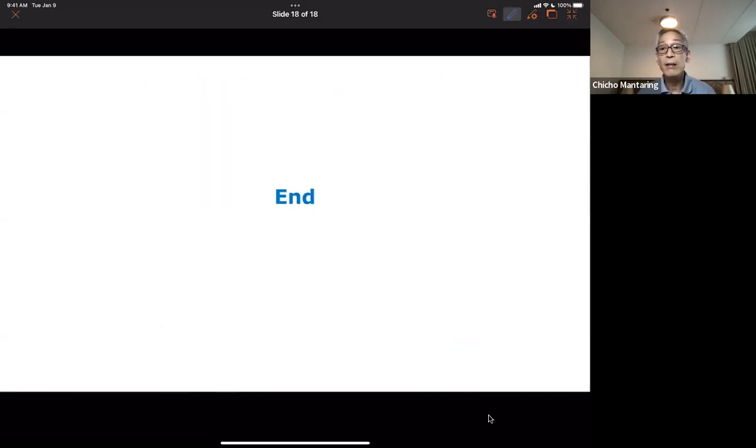So that's it. That's my presentation to you of the small signal model of the transistor. Again, just to summarize, this is just the model of the transistor by itself. Later on, when we connect components to the transistor, then you're going to have to recompute the small signal parameters, or rather the two-port parameters of your new network.